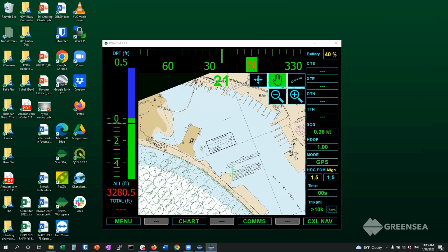And with the logging, whether you're in the water or you saw the problem outside of the water, pretty much all you do is turn on the log and try to replicate it again. Let's say it's a compass that's just going around at 360 degrees and it doesn't stop. Turn logging on, then turn logging off, and then our engineers will be able to look at it and say, yep, this is what happened, there's some weird magnetic pull, or the hardware seems faulty, or something's broken, or something's loose, which doesn't happen very often, but that's just what we'll ask for: a log.